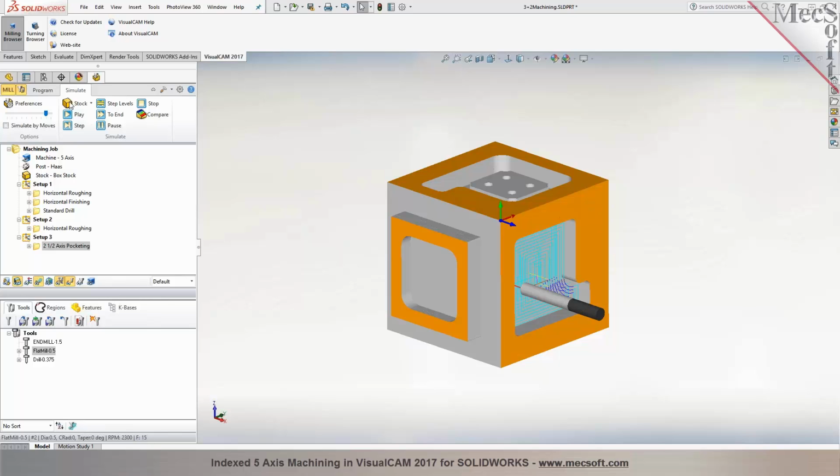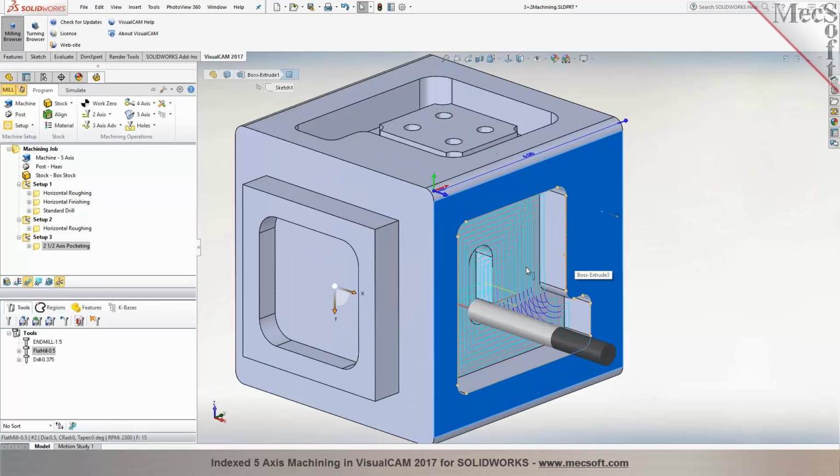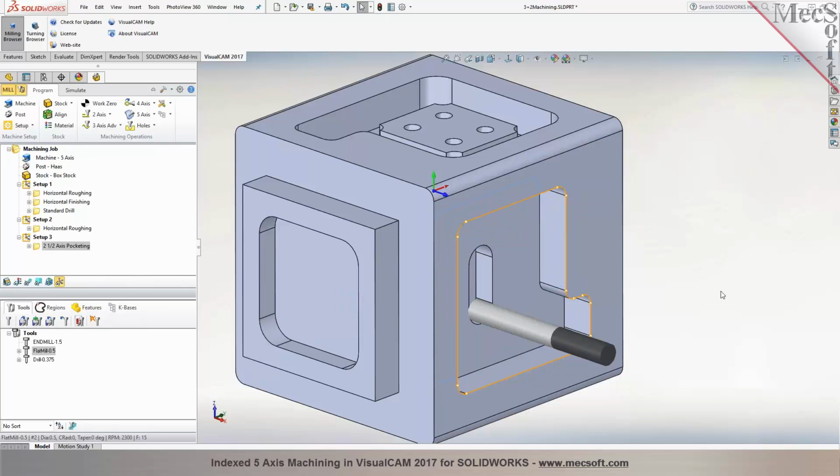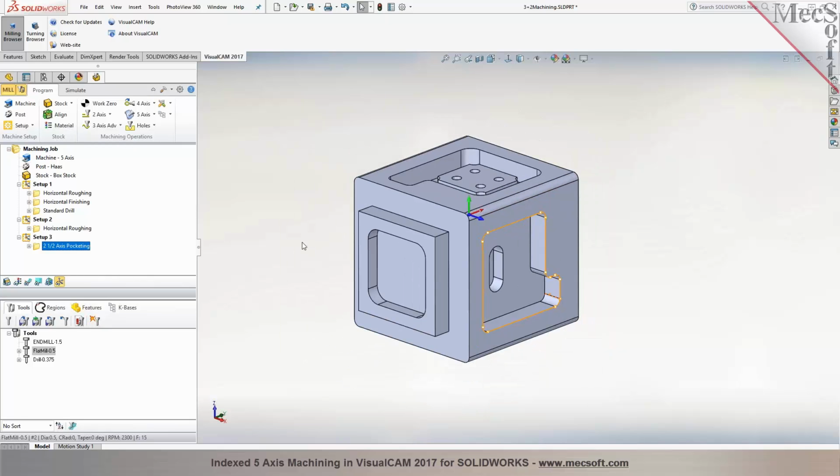You would still be setting the z-axis normal to this particular surface, but then you would program a 3-axis roughing and a finishing toolpath rather than using a 2-axis operation, since the floor of the part is not planar. So you would basically have to program it with a 3-axis toolpath. That will work better. Yes, I understand.